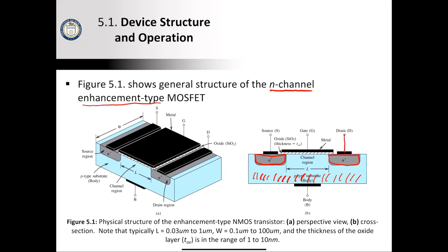Both of those wells have an attached lead. One is called the source, one is called the drain. And then here we have this two-layer piece. So up top, we have a metal connector. And the middle, which I'm coloring in with red, is a dielectric material. In this textbook, we'll generally talk about silicon oxide, but there are others that could be used.